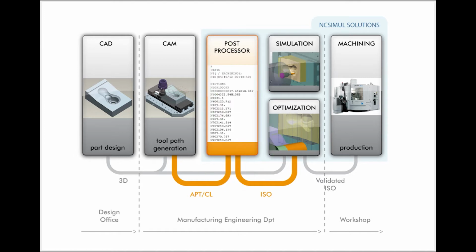This is a flow chart for making a single part from start to finish. The majority of the time is spent in the CAD program, giving the user the ability to fit assemblies, determine restraints, and run analysis. A CAM program is then used to create toolpaths prior to post-processing, which converts the software program into G-code for the particular machine. The simulation will help prevent errors prior to machining setup. Optimization is used to speed up the machining process in order to minimize cost.